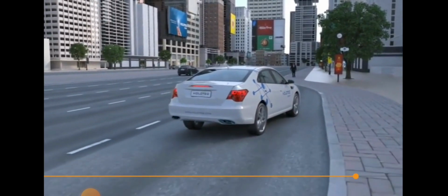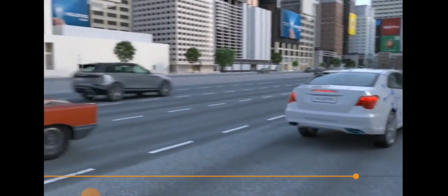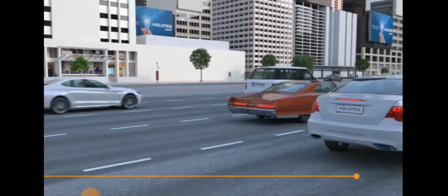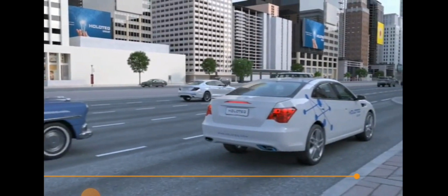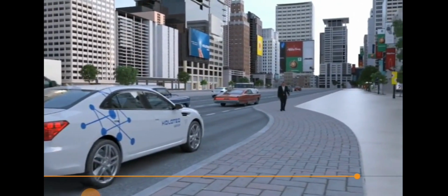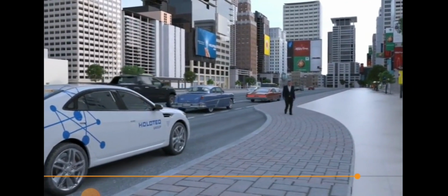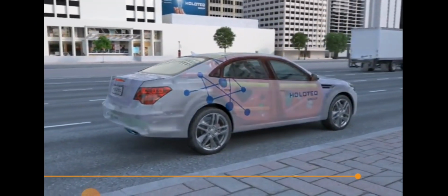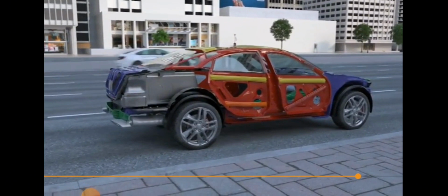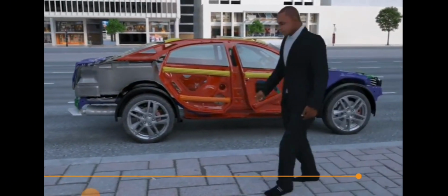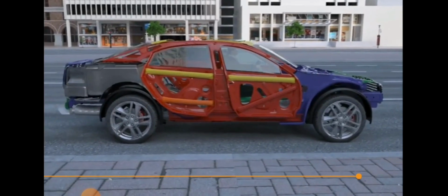Design of the body in modern vehicles. In old vehicles, the common is to enforce hardness of vehicle body to provide the required strength, but this concept changes later, where hardness design is limited to the compartment only to provide safety for passengers. The two front and rear parts of the vehicle are designed in a way that ensure absorption of collision force in accidents through performing collapsing points in the rest of the vehicle body.